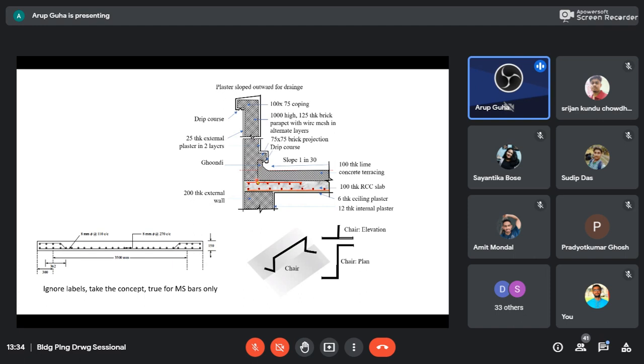The only thing is that if water enters this interface, either through the exterior or through this, then it can trickle here and it will search for the weak point in this slab, and through that it will go in. And if it comes here, it cannot evaporate either, so it will remain.